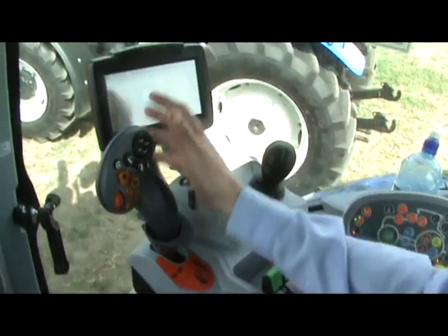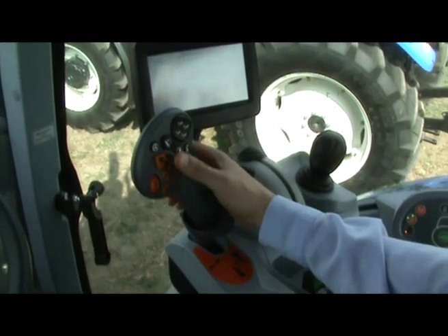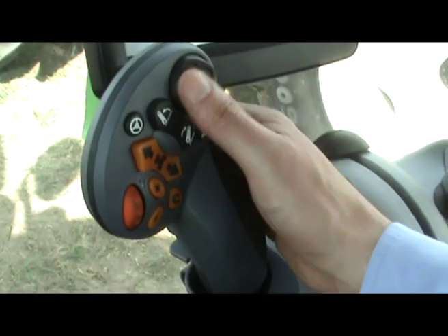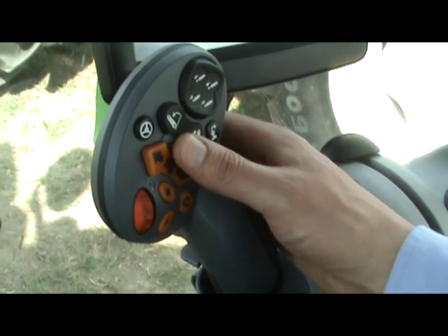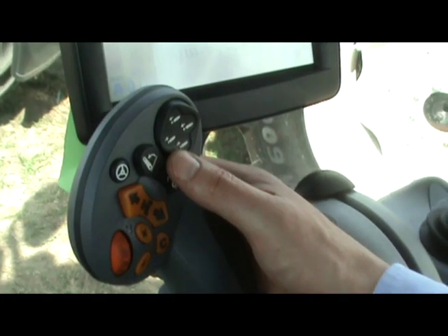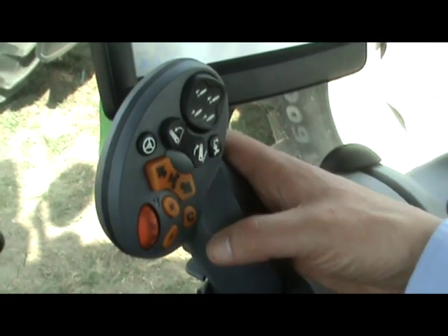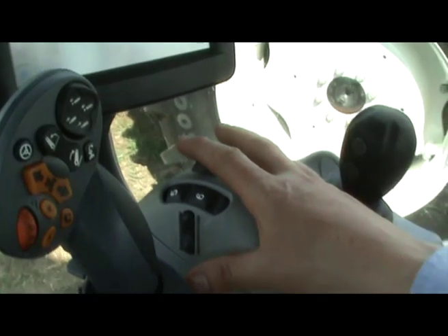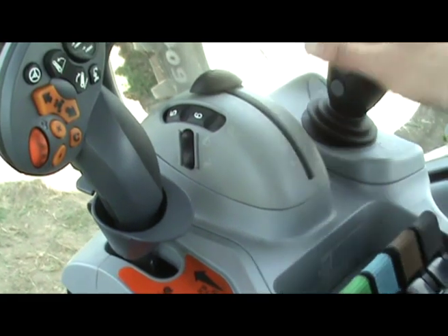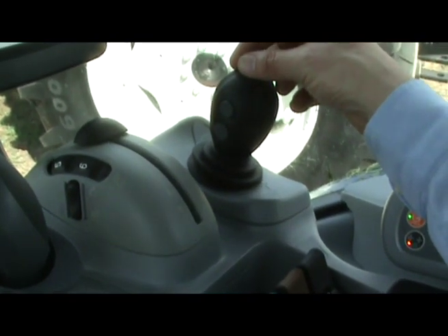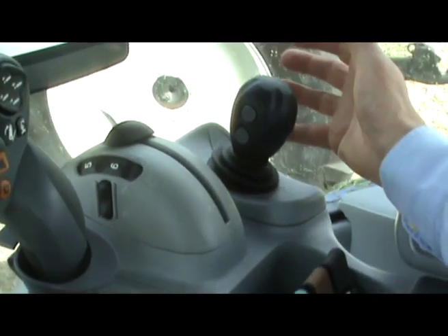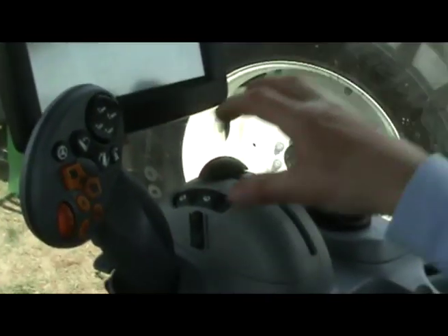Things on the Sidewinder, we've got a command grip, multifunction handle, and on here are the transmission controls, 3-point linkage and 2 remote valves. So anything to the left of this central bridge is to do with transmission, anything to the right is hydraulic controls. We've got our draft control, the New Holland so-called mouse, which is position and draft controls here, and then over here we've got a joystick which can control either the rear remotes or a mid-mount valve for a front linkage, for example. And the customer can specify where he wants these.